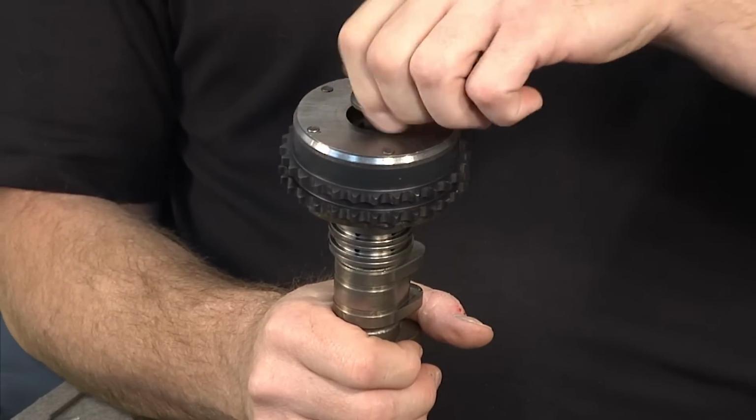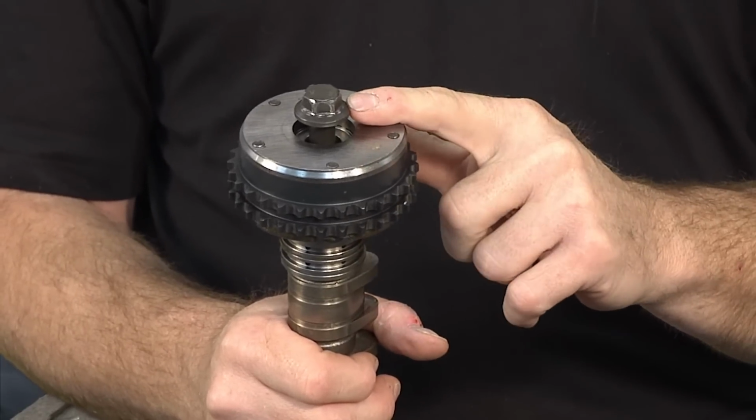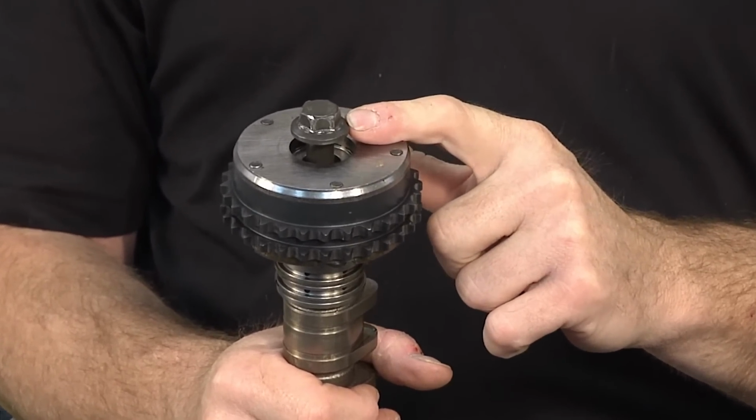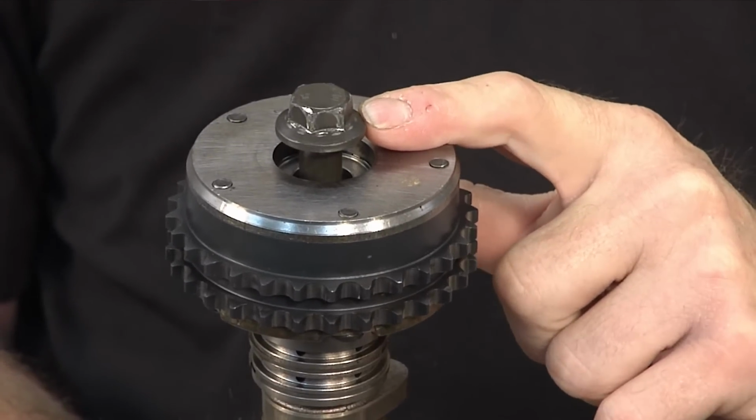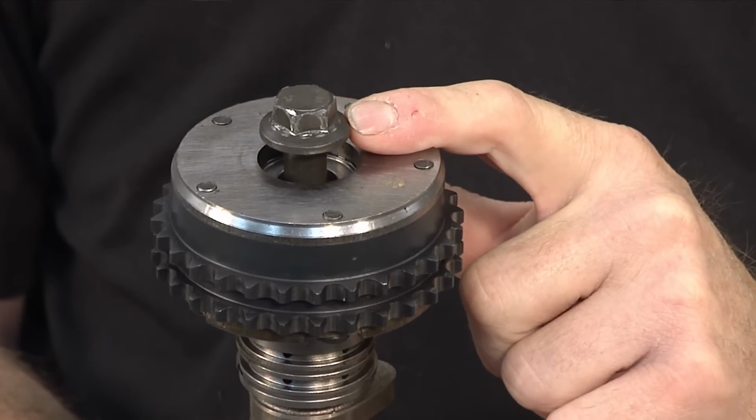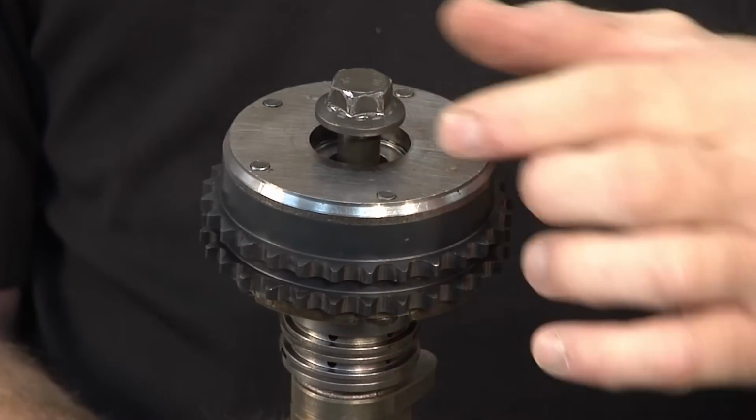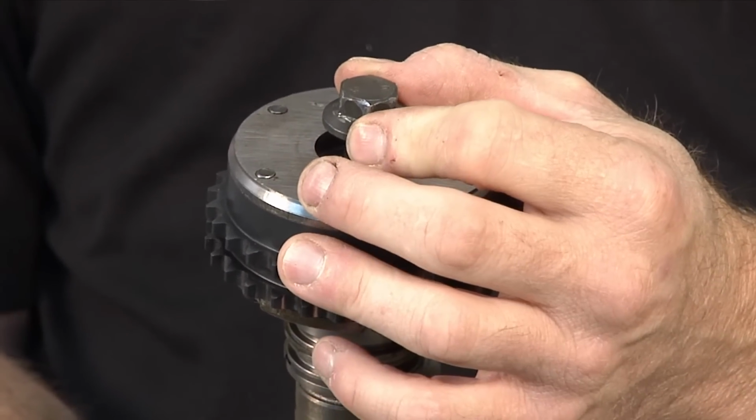And this retention bolt that I'm pointing to here is an item that must be replaced any time that it is removed. We've seen a problem with factory engines, even during warranty periods. We've seen where this bolt would have inadequate torque and it would not have the proper amount of yield when it was tightened, and it would allow the position of this valve adjuster, the vane cell adjuster, to slightly move under load. So when you torqued it down, it would allow it to move a little bit.